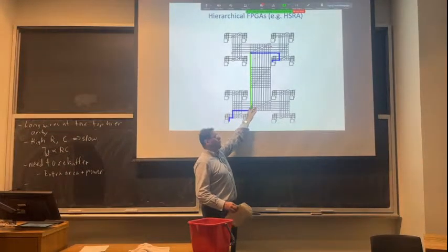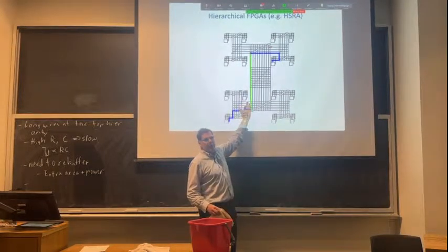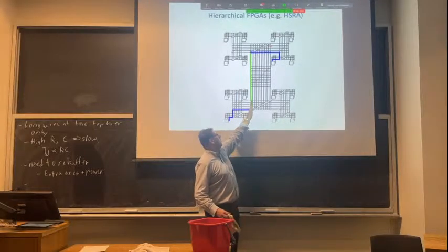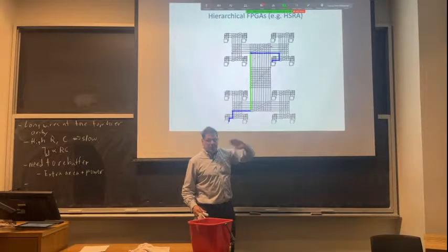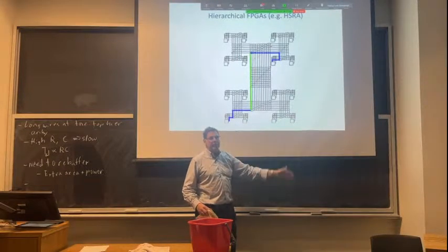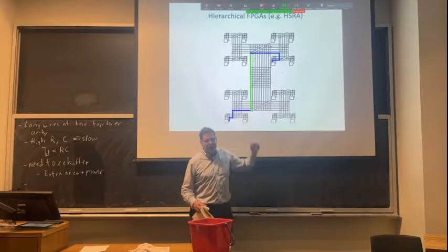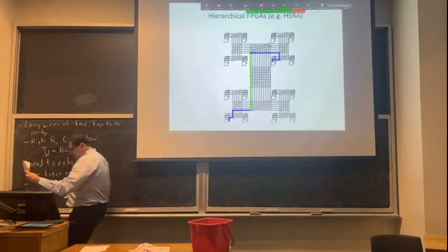This also is going to consume power. Every signal that goes over such a big piece of capacitance is going to take a bunch of power too, right? Every toggle of this wire, we charge, when we go to 0, or discharge when we go to 0, then we recharge when we go to 1. If this is a lot of capacitance, that's more power, so we don't like that. So it's not great.